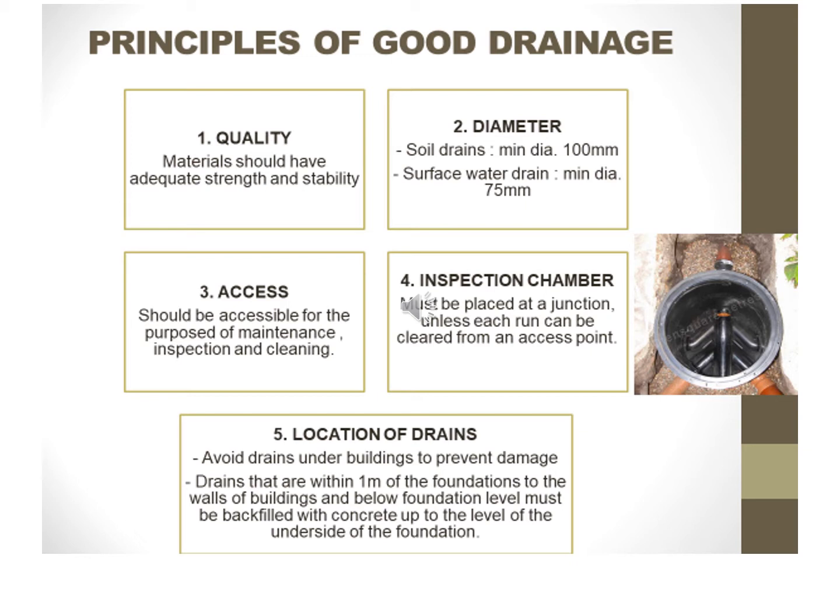Access. Drains should be accessible for the purpose of maintenance, inspection and cleaning work. An inspection chamber must be placed at a junction unless each run can be cleared from an access point.